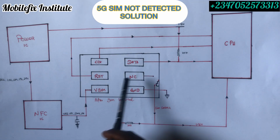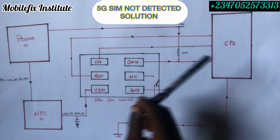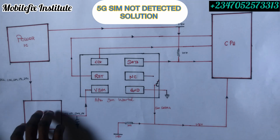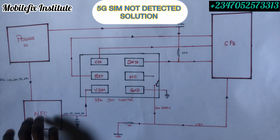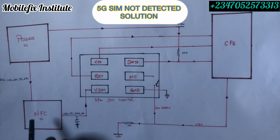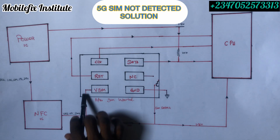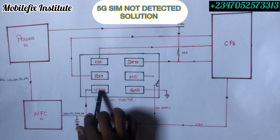Now I will show you how it works in schematics. Now how to trace it using schematics. Now when it enters this NFC IC, the output voltage will come. Now this NFC IC, this is the input voltage that powers up this NFC IC. If this NFC IC is faulty, it won't be able to generate this voltage to your SIM card tray.